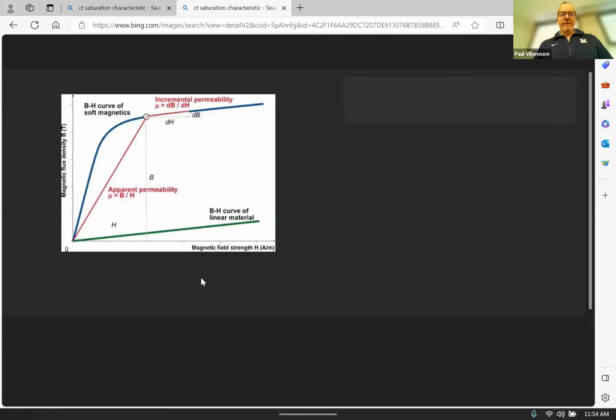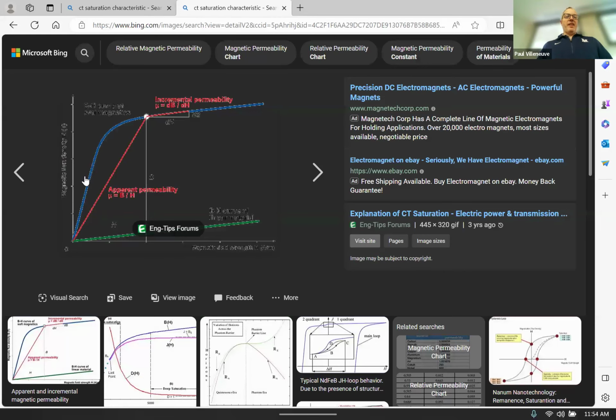So as you start driving it, it's linear. And then once you get here, you're really trying to push that hard. So now the voltage just drops. But if it was perfectly linear, it would just continue to increase the current. But it peels off. So that's the problem. It'll bend your brain because you've always assumed a linear power system, a linear power supply. These are not linear. They saturate. And that's the test.